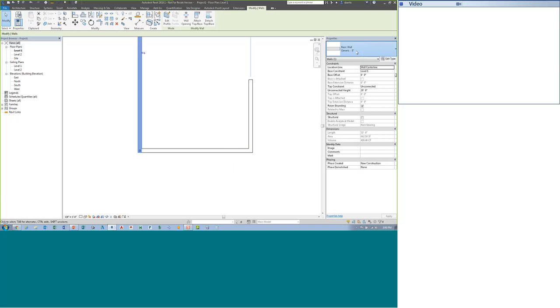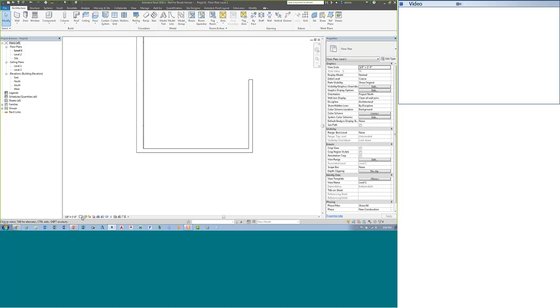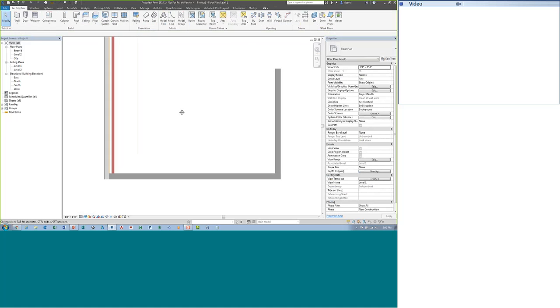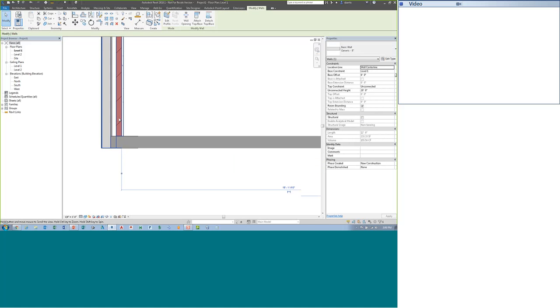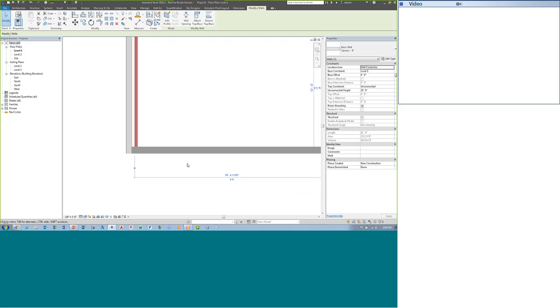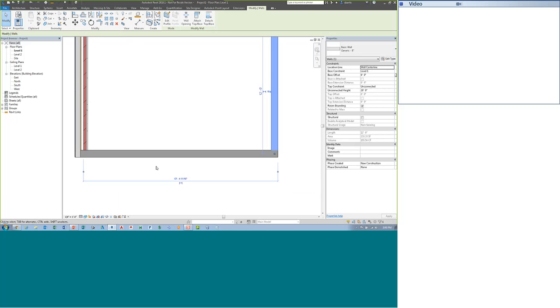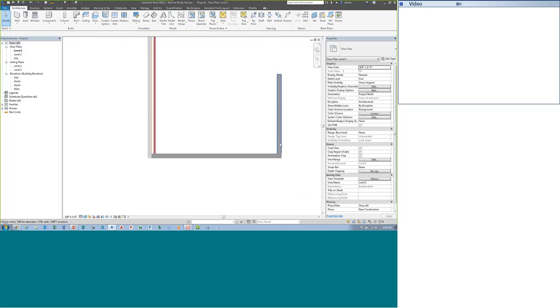If I take this wall and switch it to a different type of wall and switch this to a fine level of detail, shade it up so you can see, if I select this wall, that dot, if I click it, it jumps to one side, click it again, jumps to the other side, click it again, jumps back. If I wanted to align and dimension to the inside face of that brick, I can left-click and hold, put my cursor on that point, tab, and it will highlight that line, let go, and it will dimension to that part of the entity. Okay, so that's temporary dimension.